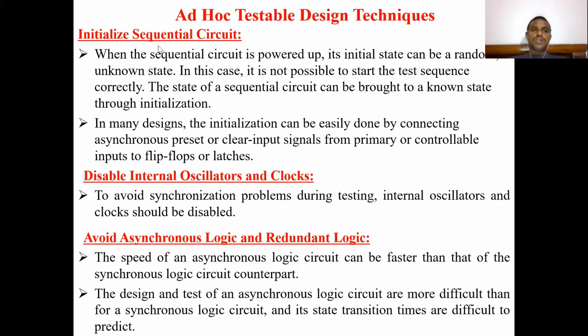That's the second technique we have in terms of sequential circuits: initializing the sequential circuit. In many designs, the initialization can be easily done by connecting asynchronous preset or clear input signals from primary or controllable inputs to the flip-flops or latches. Generally, a sequential circuit is a combination of a combinational circuit with memory elements.